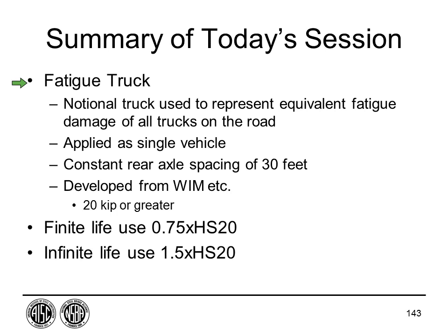That's a notional truck, not a real truck, but it's trying to give us the same fatigue damage that the variable amplitude spectrum does, all wrapped into one truck, easy to use for design and evaluation. A difference of how it's used in strength, right? Remember, in strength you cycle through 14 to 30 foot trailer spacing, where we hold it constant at 30 feet, and it's based on real weigh and motion data, so we can have confidence that it's based on real information.